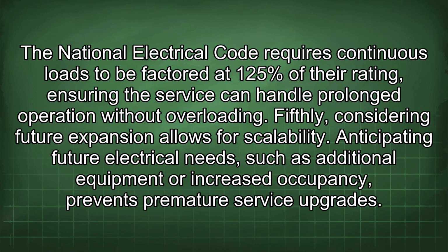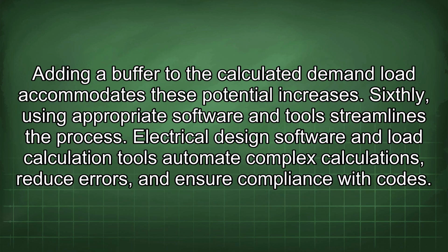Fifthly, considering future expansion allows for scalability. Anticipating future electrical needs, such as additional equipment or increased occupancy, prevents premature service upgrades. Adding a buffer to the calculated demand load accommodates these potential increases.